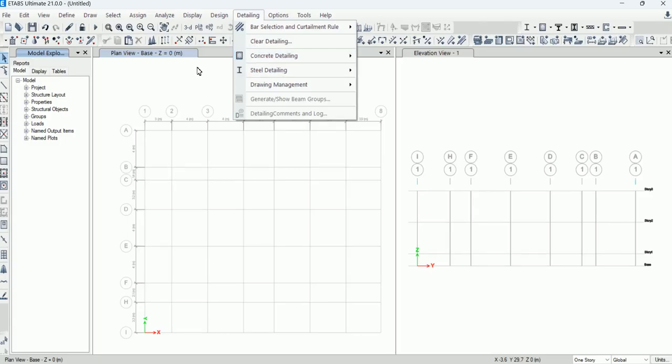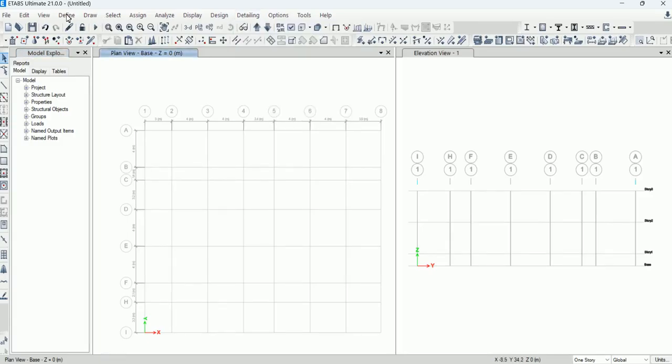So we are going to define. I already have the beam and column sizes, so let me check the size of the column, depth or width. As per the architect's requirement, I have the size of the columns. I have three types of beams, so I will use those and define those beams.